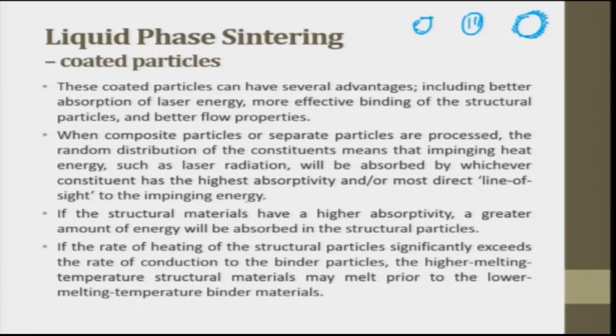Line of sight is the laser hitting a surface; at that surface, do we have the material which can absorb more? If the structural material has a higher absorptivity, a greater amount of energy will be absorbed by the structural material. Right, that is what I said. It can have varying absorption. This is structural, this is coating.